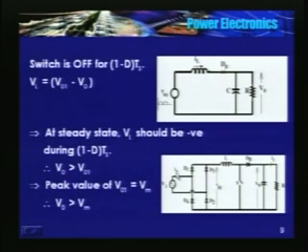Current is a sinusoid, therefore the RMS value is the same as the fundamental component. So the power factor becomes approximately equal to 1. So the entire bridge along with this resistor load appears like a resistive load to the source, since Is is a sinusoid and is in phase with Vi.